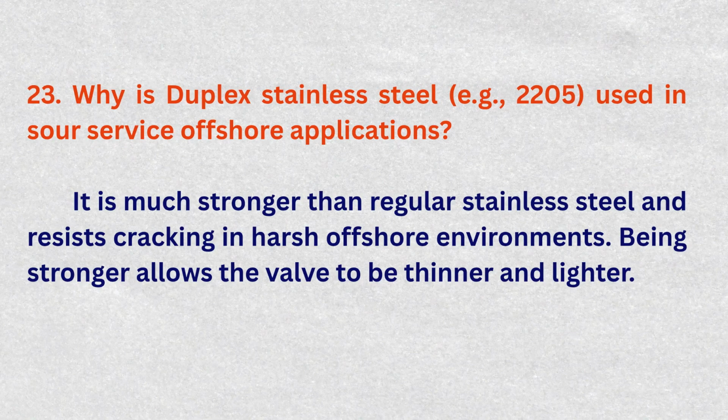Why is duplex stainless steel, for example 2205, used in sour service offshore applications? It is much stronger than regular stainless steel and resists cracking in harsh offshore environments. Being stronger allows the valve to be thinner and lighter.